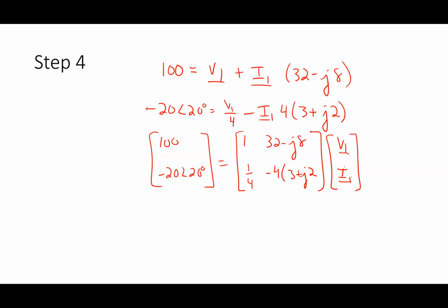So you said you want to find the V1 and I1? Well, once I turned the crank on this, I'd solve for V1 and I1, right? Once I have V1 and I1, how would I get V2 and I2? You get V2 with just V1 over 4. Yeah, so V2 is simply V1 over 4, right? So I would just take that phasor and divide it by 4. There'd be no change in the angle, I'd just be changing its magnitude by dividing by 4.